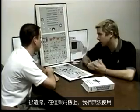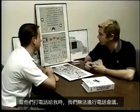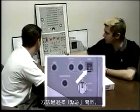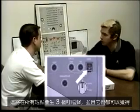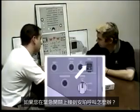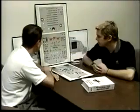Unfortunately, on this airplane, we can't conference call by using the forward and aft calls, and when they call me, we can't conference call. Really, the only way you can conference call with the people in the back is by selecting emergency to on. That'll give 3 dings in all the stations, and they can all get on and talk as a conference. What if you were to get the amber call on the emergency switch? That means that they are emergency calling me from the back.